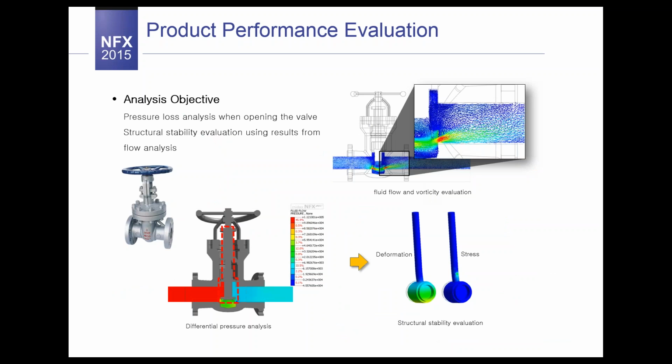Now, coupling of fluid pressure calculation with structural analysis through fluid structure interaction is useful to detect the impact of the inner fluid on the product. As you can see in this example of a valve, you can analyze the flow, then you get deformation and stresses on the structural model, and then you know how to improve your design.